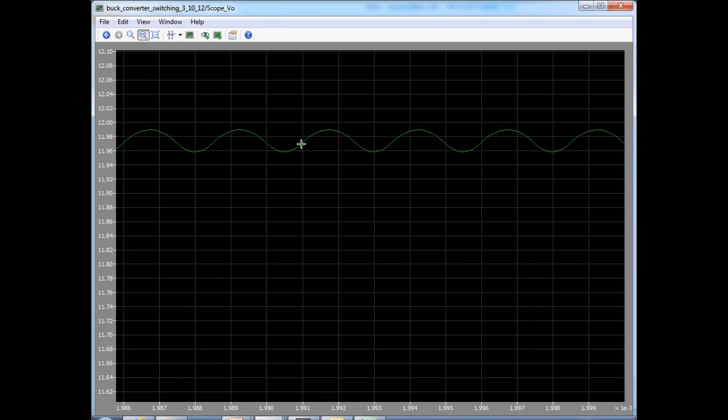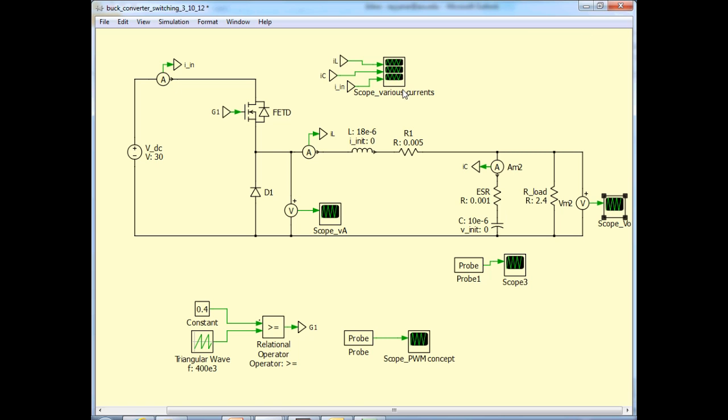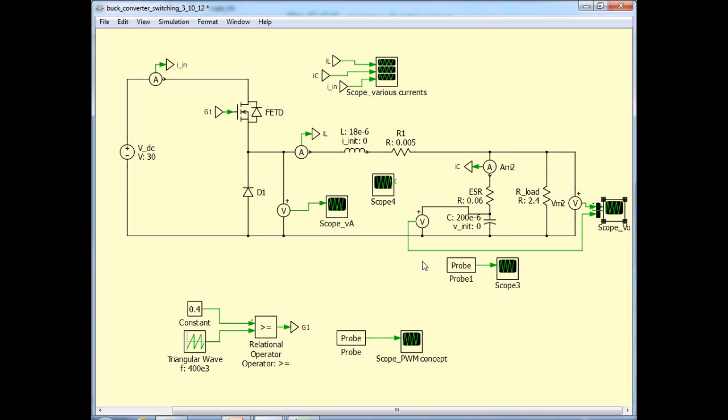So once again, this is the integral of the capacitor current, and therefore it is closer to a sinusoidal or parabolic waveform. This is the integral of the triangular waveform, which is the current. So this is exactly what we expected for a low capacitance and negligible ESR design. Most of the other waveforms, like the inductor voltage or the inductor current, would remain exactly the same as in the previous larger capacitance design. So we don't need to look at them again.